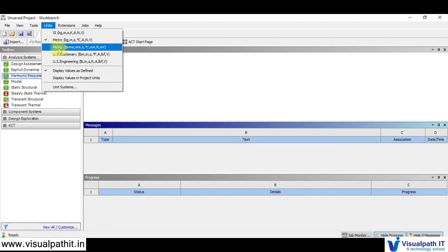So we should be very careful when selecting the unit system. The unit system used in Ansys should be consistent with the geometry. Say you have some geometry built in millimeters, so the unit system is millimeter, ton, like that. But when you import into Ansys, you import using the SI unit system. That mismatch can change the entire scenario, because then a given value corresponds to 1 meter or something like that. It can cause a lot of confusion if we don't set it properly. So our unit system should be properly defined, and it should be consistent with the CAD geometry.